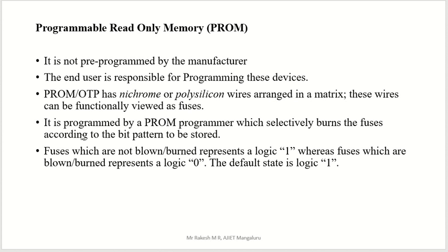That means we are going to program. It is programmed by a PROM programmer, which selectively burns the fuses according to the bit pattern to be stored. That is called burning the fuses. Fuses means a lot of polysilicon wires arranged in rows and columns.